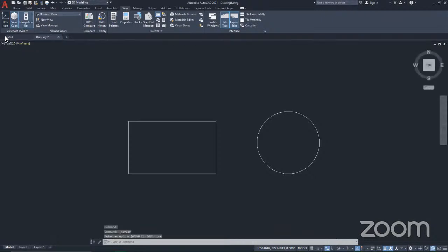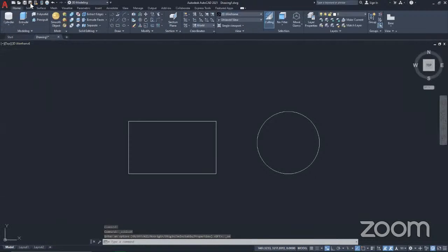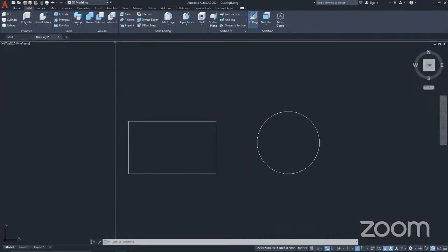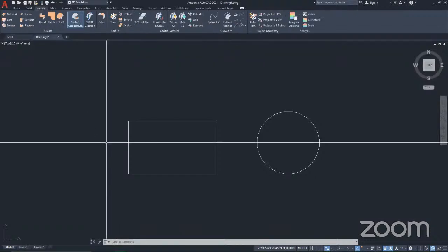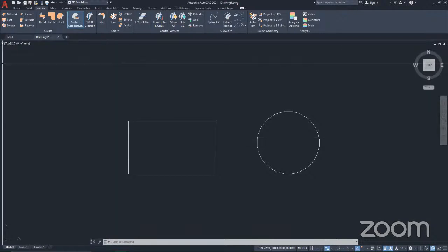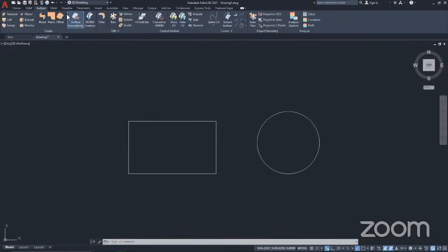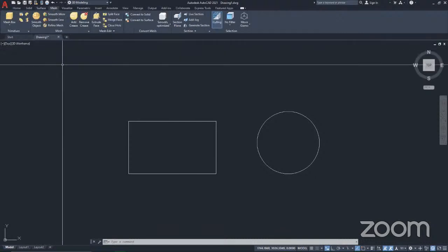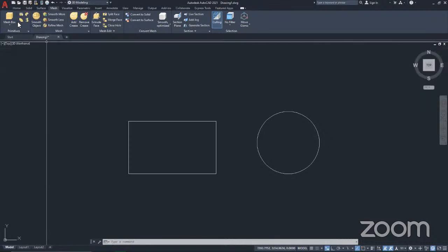We're going to activate them back like so and go back to our drawing. Where was I? Okay, now solid editing will help you create solids, and surface editing will help you create surfaces. Mesh editing, of course, if you want to do some extended kind of editing, you need some mesh also to do some patching and all that.